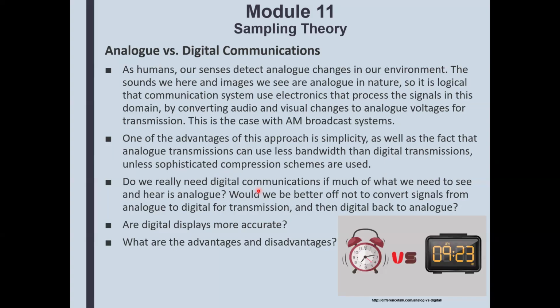It was supposed to display the voltage from 0 to 10, and what we implemented as a display was an integrated circuit with 10 LEDs. It was bars, going from one LED to 10 LEDs. And depending on the voltage applied to the circuit, this would light up 3 LED bars. That means we are measuring something around 3 volts, and so on.